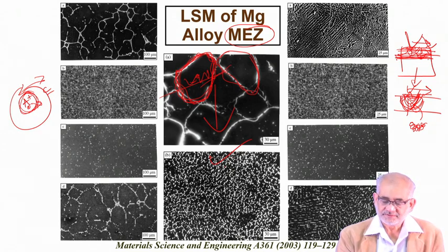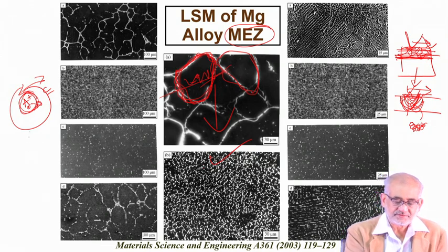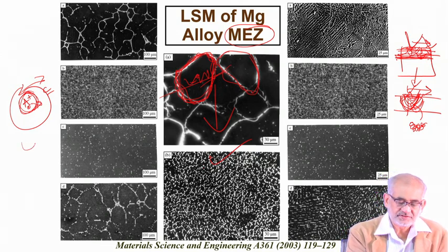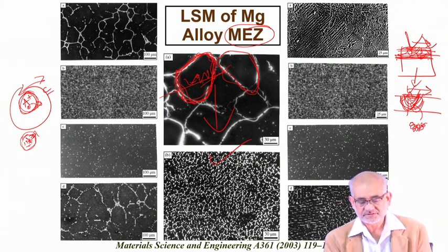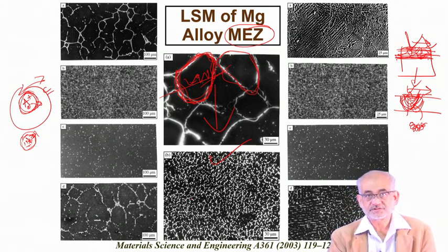One is improvement because of grain refinement and uniform distribution of these intermetallic phases, the hardness and the wear resistance improves. And on the other hand, another very important advantage is that from this microstructure, when you create very small crystallite size, where the distance between the core and the surface is so small that you cannot create a potential galvanic cell between an anodic and cathodic part. So in other words, if these cathodic components get distributed all over, there is no easy formation of any galvanic cell in the microstructure. So the corrosion property also improves. So you get twofold improvement of wear resistance and corrosion resistance.